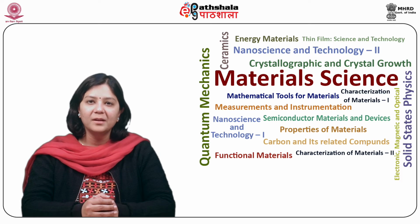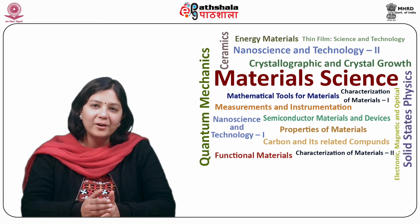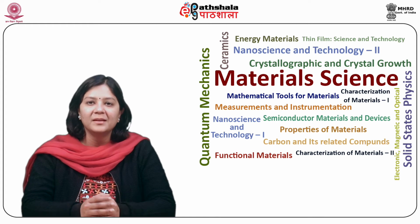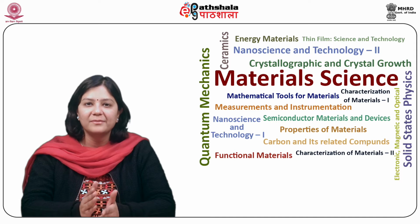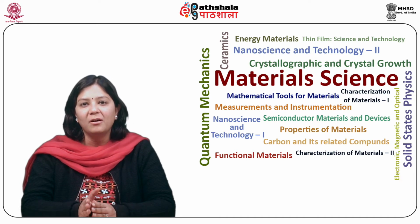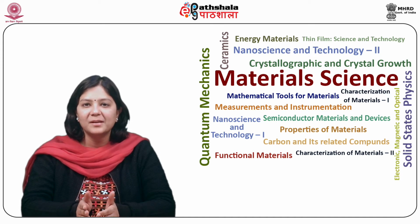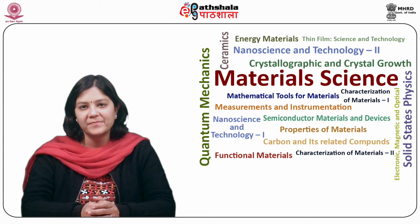Photolithography, or optical or UV lithography, is a microfabrication technique employed to pattern parts of a thin film or bulk of a substrate. The desired geometrical pattern is created on a photomask. This pattern is transferred from the photomask onto a light-sensitive material, often termed as photoresist or resist, on a substrate. Further chemical treatments are done to engrave the exposure patterns on the substrate.